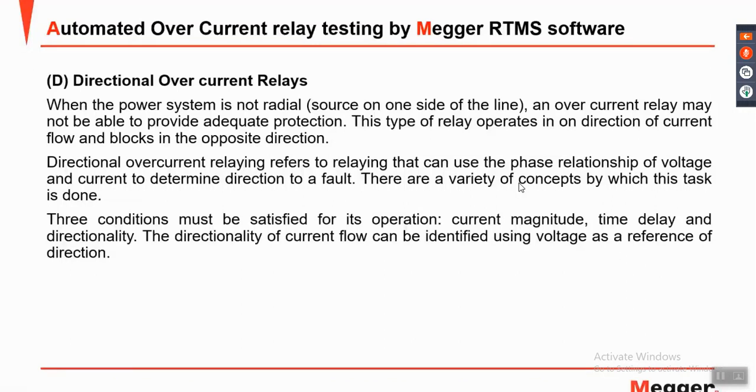So it is like selectivity. If we have it selected, we'll have a direction. It means that when I have two parallel lines, if I have normal overcurrent in the other direction and a fault, it may do an open end, while with a directional overcurrent relay, there will be correct coordination. And it will look only at a forward fault, not a reverse fault.